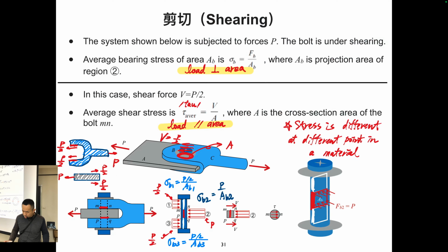Okay? Yes, the shear. Firstly, you will see a bearing force, because when you have a shear loading, you must have an opposite force. So you must stop something. The material must stop the force. So when you have the stopping force, you can call it bearing force.